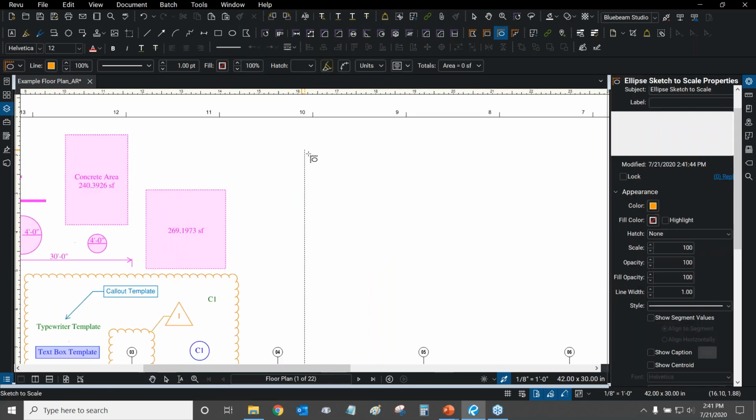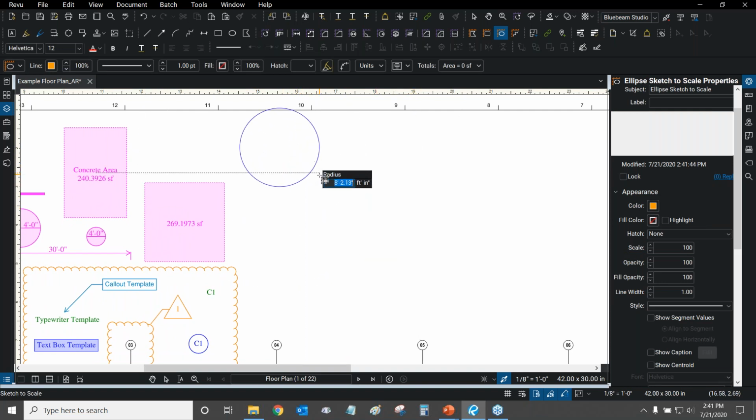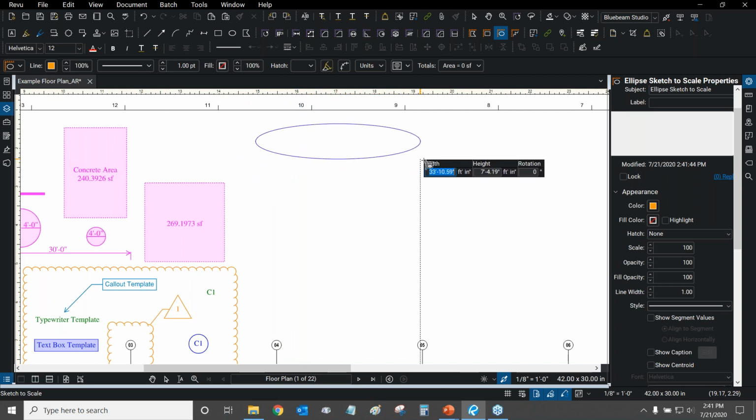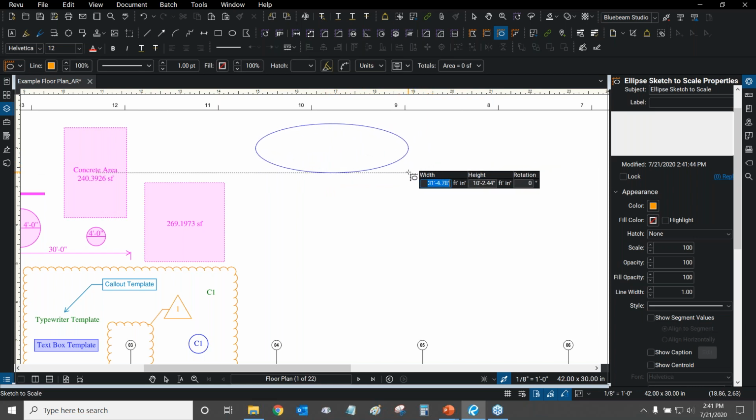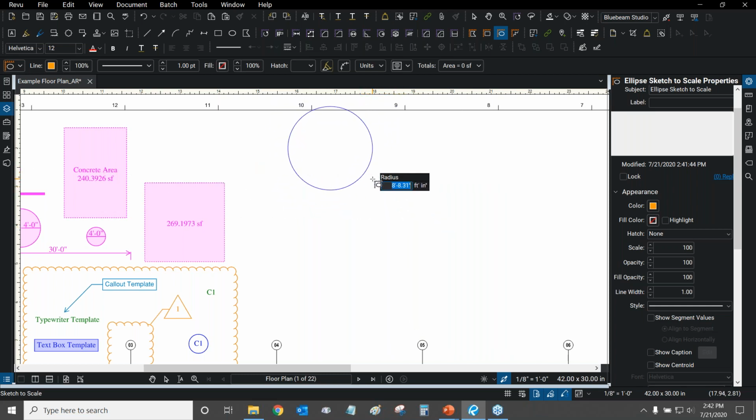Let's look at the ellipse one really quick. Don't worry, it's not just an ellipse tool, although that is quite nice. Whoops, looks like mine remembered that last time I pressed the shift key, so mine is making perfect circles. If I press the shift key again, or control key, excuse me, now I can make an ellipse. So you'll notice that the dynamic input, as I like to call it, is changing when I press control. Right now, it only has a radius because I pressed it to change between the ellipse tool and the circle tool.